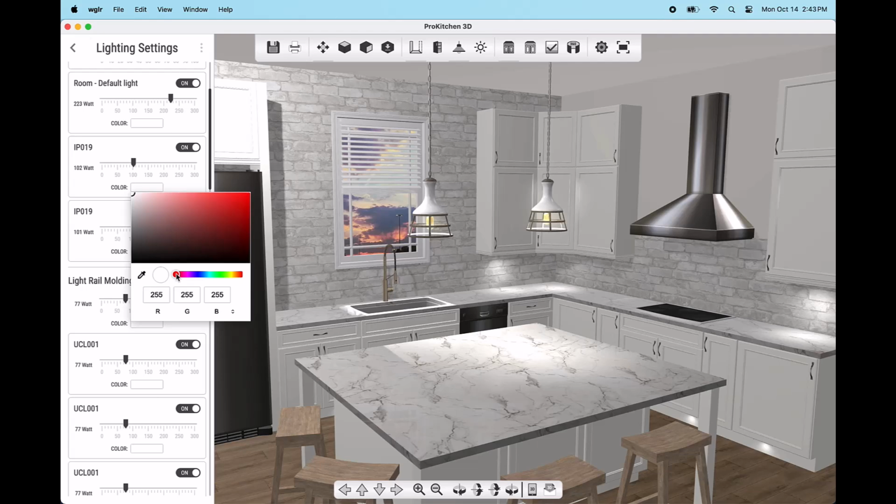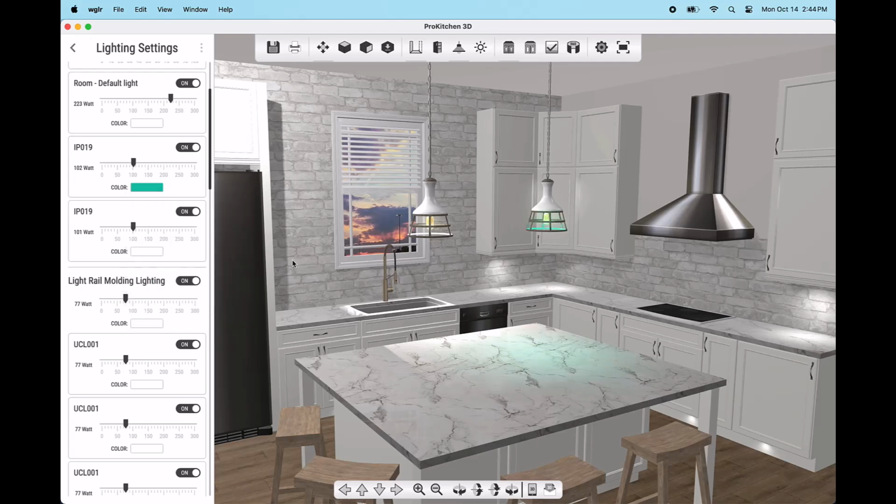Left-click and hold the red dot at the bottom of the color panel to slide through the color spectrum. Drag to the desired hue, then left-click within the gradient area above to see the color in the sample preview area. Once the desired color has been selected, left-click anywhere away from the color control panel to apply.